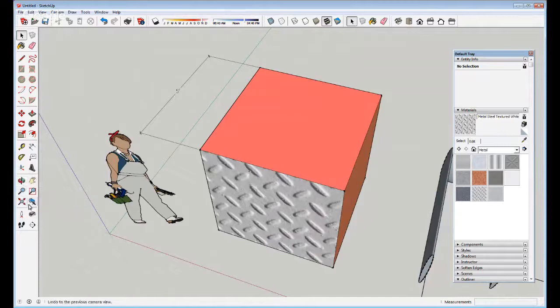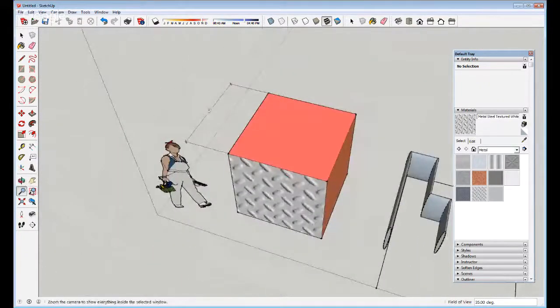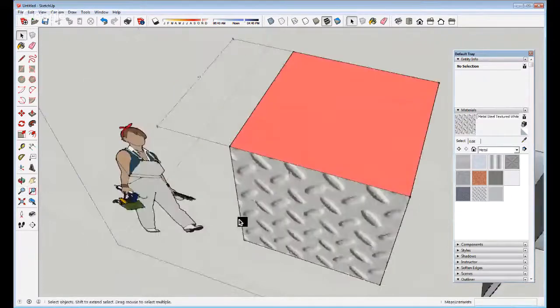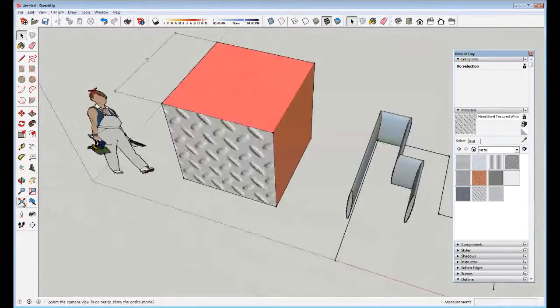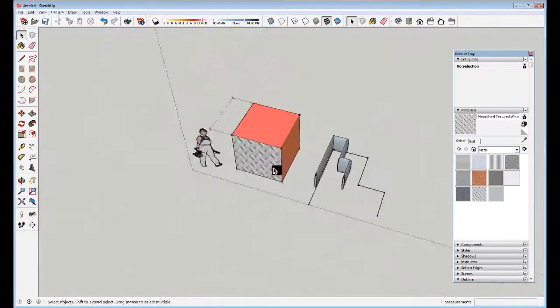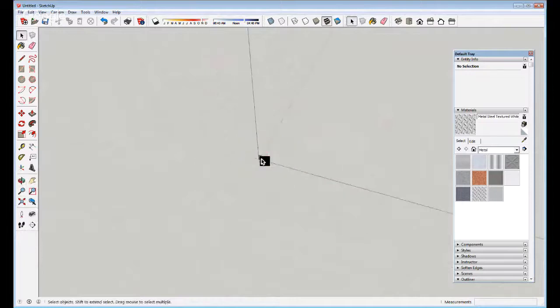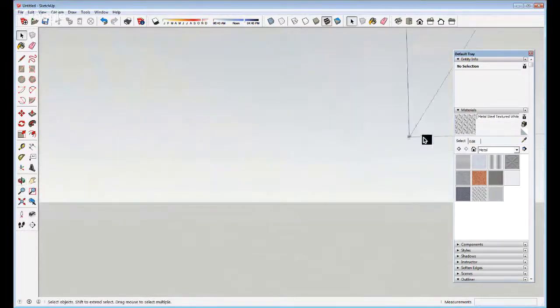This is your series of view tools, so that if you want to zoom in and out, or create a zoom window, so you're zooming into a very specific portion, that's actually pretty handy. Zoom extents is one of my favorite zoom features, because let's say you are way out here and you can't tell where you are, and you think, oh no, where'd my model go?